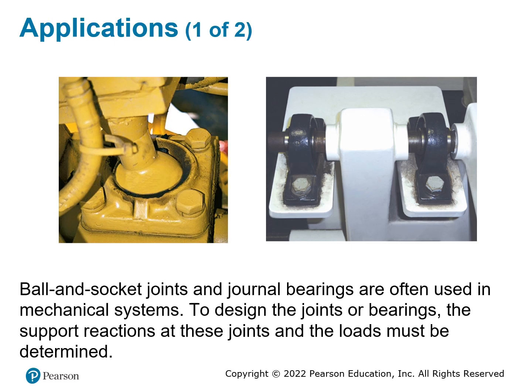Over here you see a bearing. A bearing is normally a device that supports the object but allows it to rotate. When things can freely rotate, that means there are no moment reactions. However, the bearing housing here and here prevents the bearing or the shaft from moving left and right and sometimes back and forth.